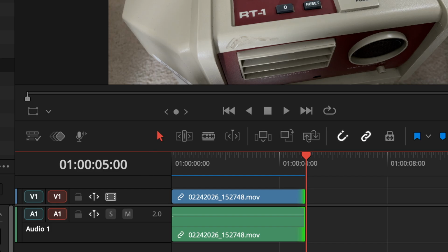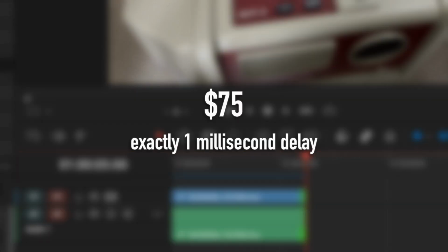Not bad. In point of fact, when I first did this with my initial value, I was about 1/3 of a second too long. So I kept subtracting from that initial LDAB instruction until I nailed it with Hex 7.5. The difference between what I calculated and what worked in reality probably has to do with other instructions in the program that I didn't account for, and the fact that the robot's OS is still running an interrupt routine to scan the keyboard, check sensors, etc. For now, what we have is definitely accurate enough.